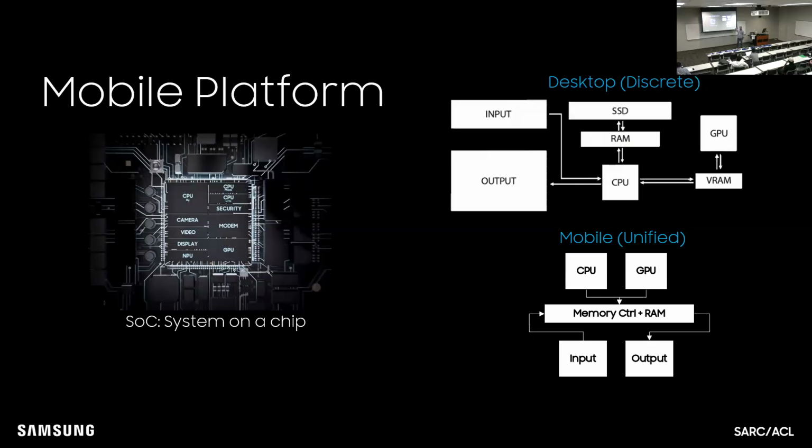On a desktop, they have something called an aperture into RAM, or an aperture into video RAM, and you have to point to that specific part, lock it, write to it, and then say I'm done, and then the graphics card can read from it, and there's a handshake. And they get away with it because they're going fast enough and their frequencies are like 2 to 3 gigahertz, and that's great. But for mobile, we have to make a lot of trade-offs.